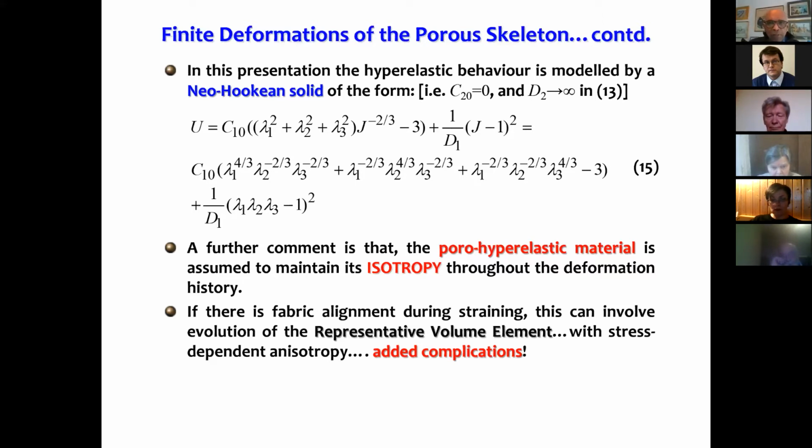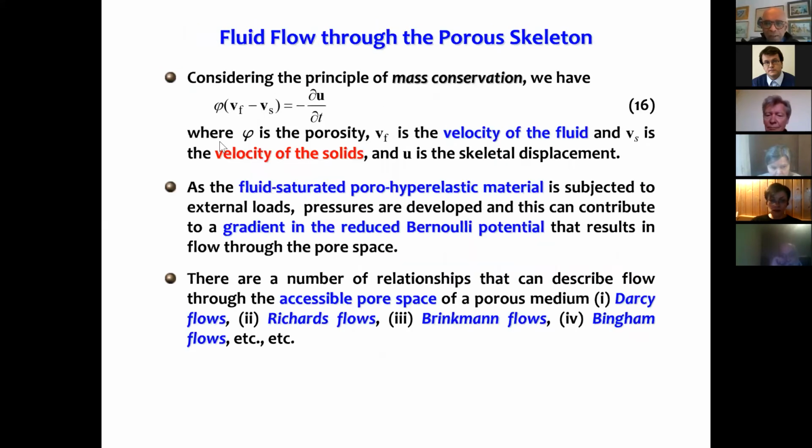What about the flow through the porous skeleton? We have flow through the porous skeleton. We have the mass conservation principle, which is this. Here's the velocity of the fluids, velocity of the solids. So when you have large deformations, the fluid moves, the solid moves. It's the relative velocity that needs to be considered in the mass conservation equation. And that gives us this relationship.